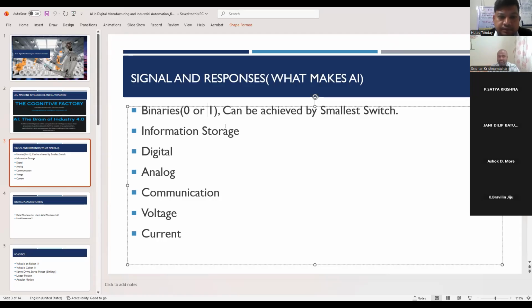Initially, for example, let us take the battery manufacturing industry itself. There are almost 20 to 35 processes involved to form a final product. Each and every product will require a manual transition of data. For example, if you try to manufacture one battery, it will follow 14 steps. First, you need to create a grid, and again you need to cure, and again you need to make a pasting of lead oxide into it, and again you need to cure, and then a burning process, assembly, acid dipping, and finally testing, and then finally sales.